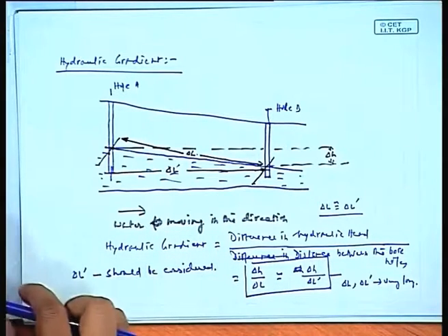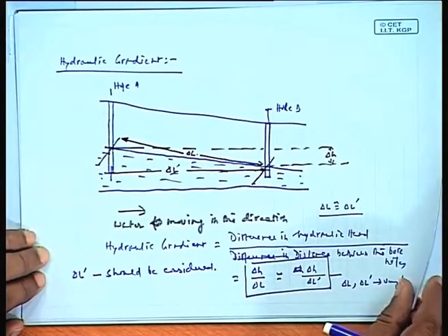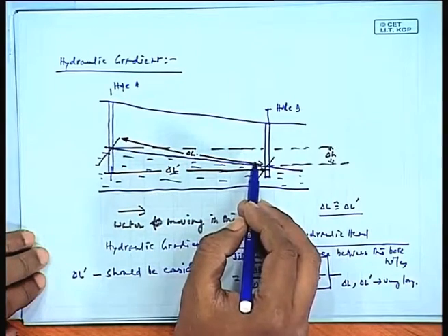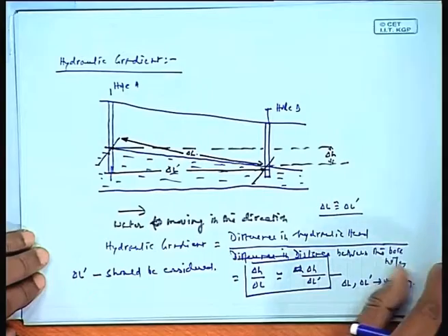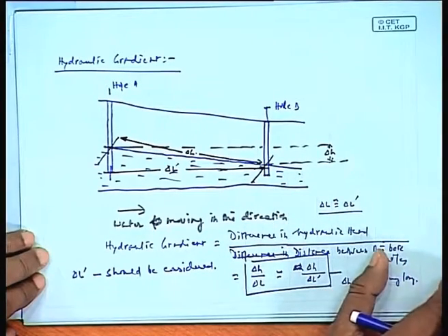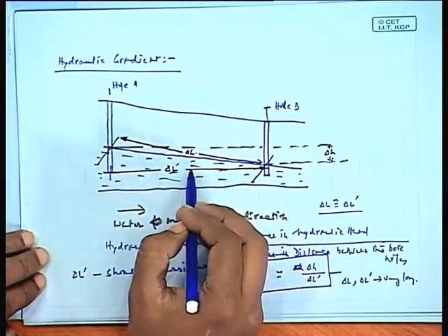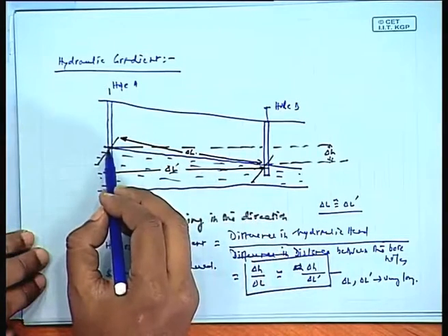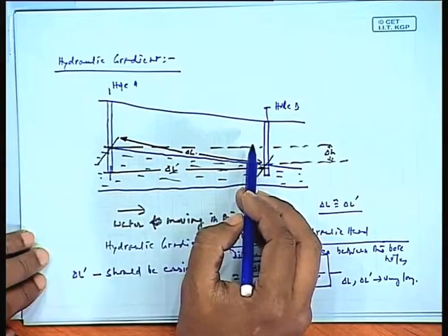Now, having said this, let me explain how we can generally find out the hydraulic gradient. This is about a two-hole case, which is a straight case, but in many cases it may not be so straight. So far there is no problem in this. This is only an aquifer. We are trying to observe the flow direction, and to observe it, two boreholes are driven at a distance.